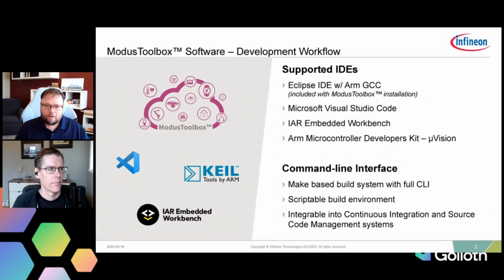When we look at what comes supported out of the box with Modus Toolbox, there's a variety of IDEs that you can use. So when you install that tools installation, you actually get an Eclipse IDE bundled with it. So you can use the Eclipse directly out of the box. It uses the ARM GCC compiler. But if you prefer not to use an IDE or have other preferences, we have full support for Microsoft Visual Studio Code. You can use third-party IDEs like IAR's Embedded Workbench, or the ARM Microcontroller Developer Kit with the Keil MicroVision IDE. And those are all supported out of the box. And I'll touch a little bit more on that in an upcoming slide.